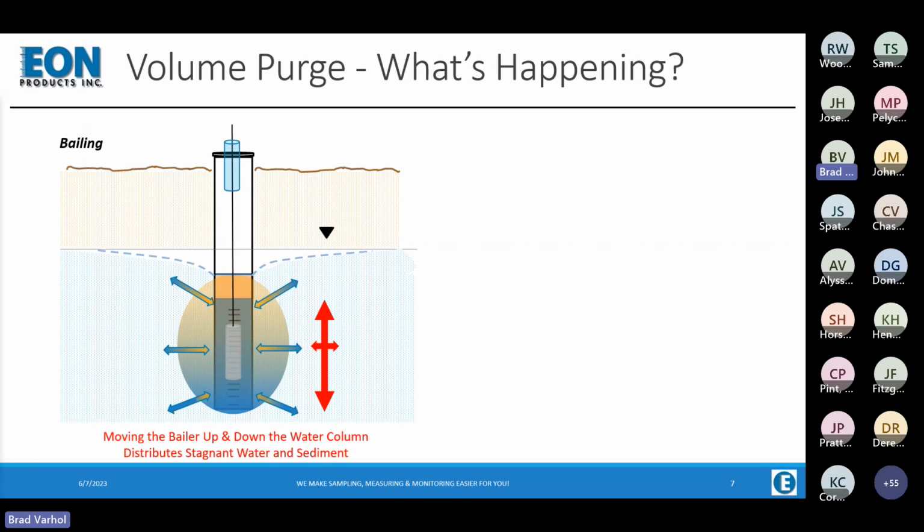of the water. But because of that stagnant water, every time the bailer is lowered into the well, it has a bit of displacement. So the water level in the well rises until the bailer starts to fill. And while it's rising, it has a pressure head that pushes some of the water back out in the well screen. Then that bailer runs through the stagnant column and drags down whatever is in there that is not the same as the aquifer, and pushes some of it out through the screen and into the formation. So as we run that bailer up and down, we have this piston-like effect that's mixing the water and moving it in both directions.